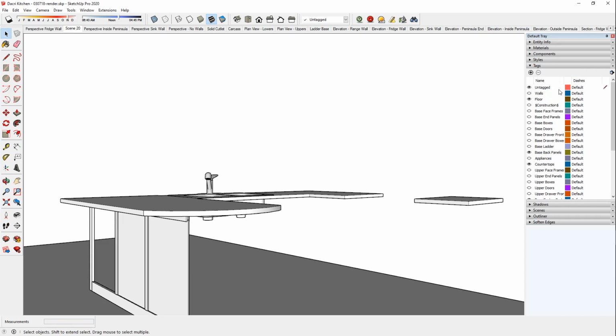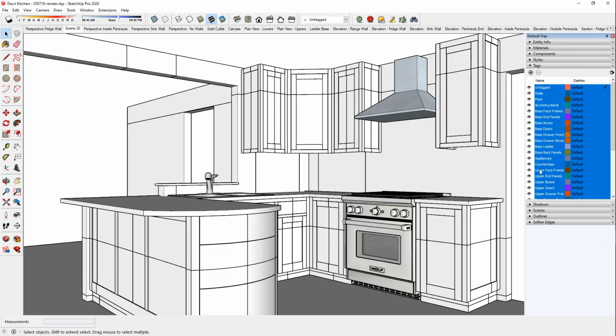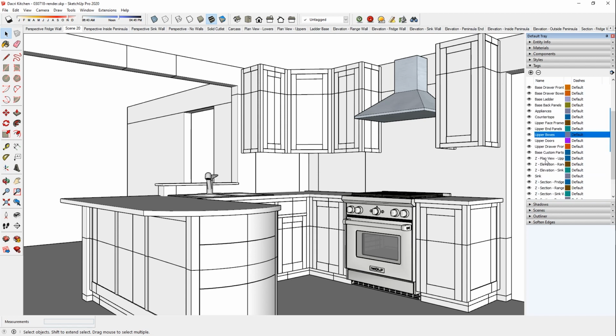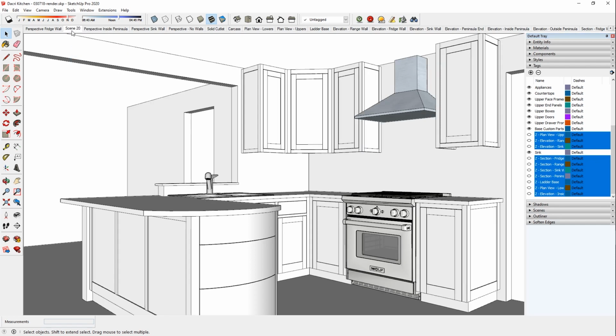And we will use this Select All function, and we will turn them all on. And then we will go down and choose the layers with a Z at the beginning. I'm going to Shift select all of those. I'm going to Control select this sync layer to unselect it. I'm going to disable those layers by turning them off. And now I'm going to right click and update. And for some reason now, when I click on the scene, it should work perfectly.